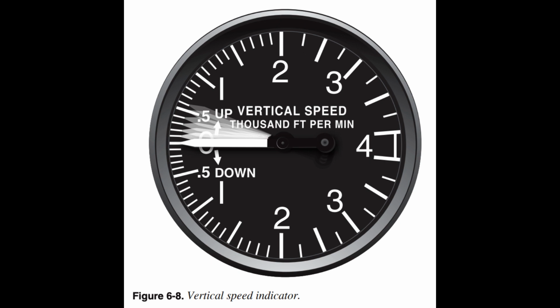Initial movement of the needle indicates the trend of vertical movement. The time for the VSI to reach its maximum point of deflection after a correction is called lag. The lag is proportional to speed and magnitude of pitch change. In an airplane, over-controlling may be reduced by relaxing pressure on the controls, allowing the pitch attitude to neutralize. In some helicopters with servo-assisted controls, no control pressures are apparent. In this case, over-controlling can be reduced by reference to the attitude indicator.